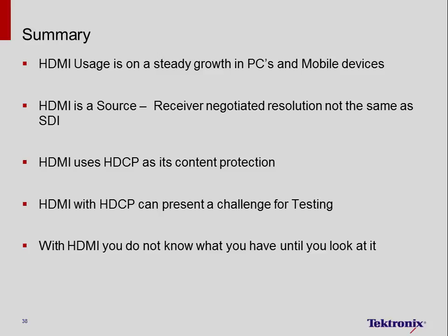So in summary, HDMI usage is on a steady growth path in PCs and in mobile devices for video. HDMI is a source receiver negotiated resolution, not the same as SDI, where SDI is a feed-forward resolution.